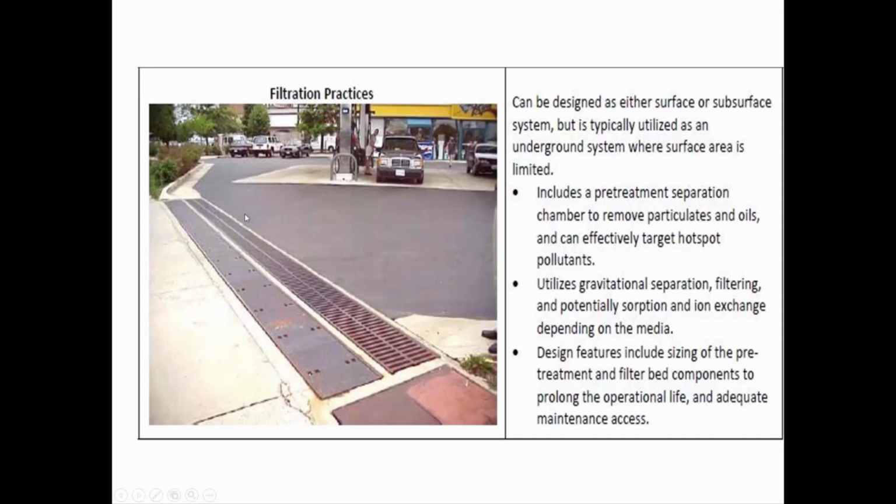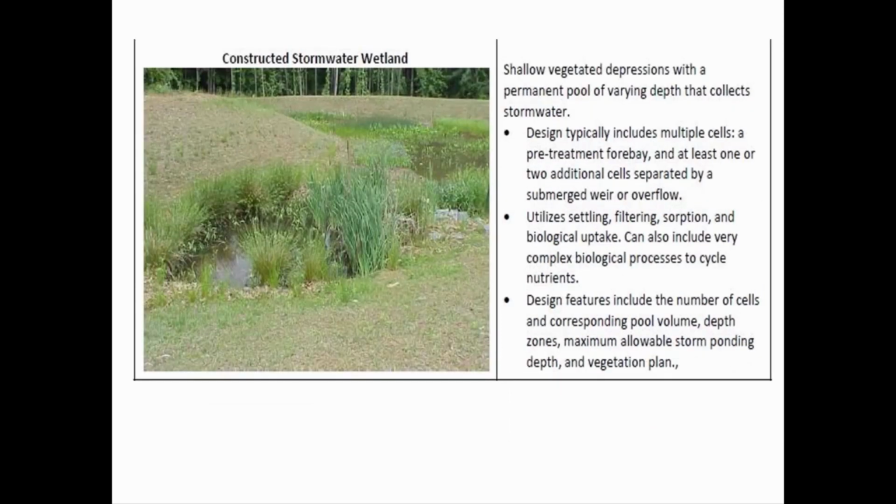And if they get into the water, that can infiltrate down into the groundwater. It can have effect on the fish and the birds and the insects that live in streams. And so finding ways to capture especially polluted water like that at a filling station is important. So it may be something like a passive filtration where just by gravity you're separating oils from the top, sediments from the bottom, and maybe a separate pond where the organics can vaporize out before they get into a stream.